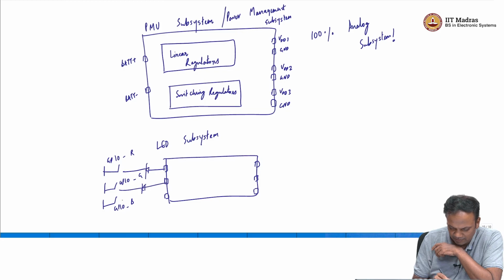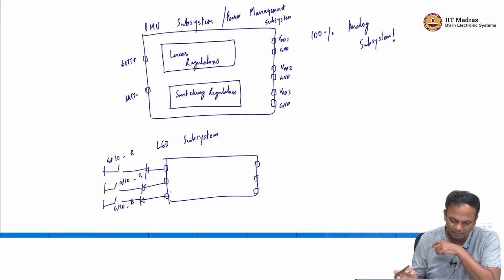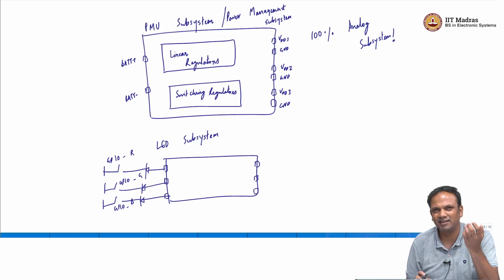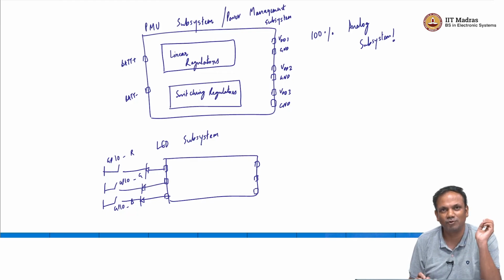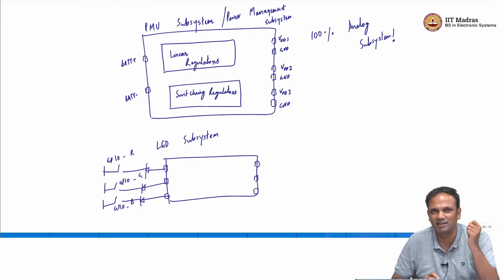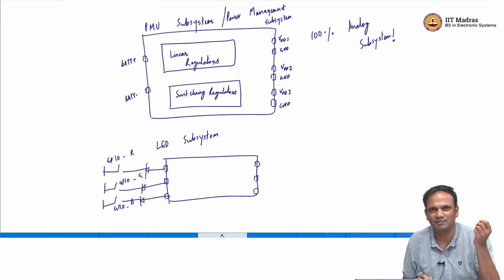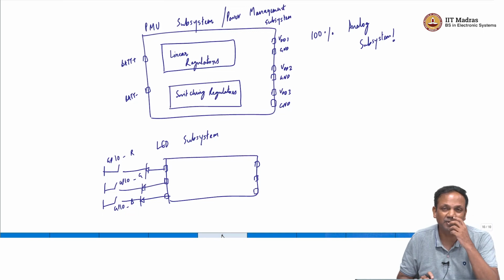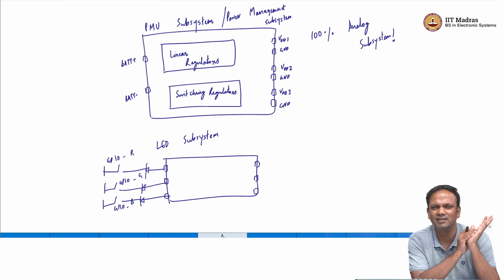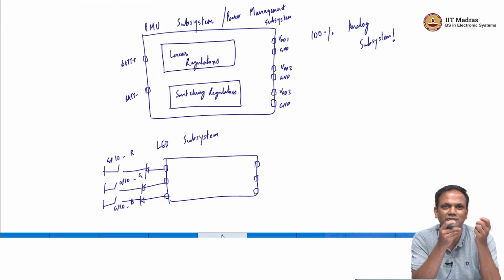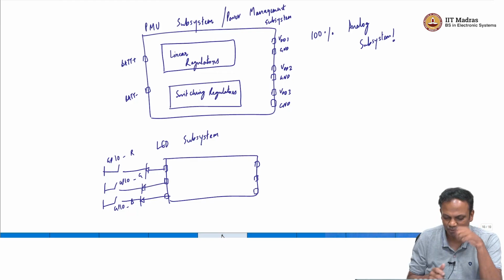So, you have the different LED lights here, and these lights need to be driven from the supply now. The way LEDs glow is that you flow current into a diode, it will glow. So, the simplest way to generate a current is to have a supply and a resistor. It is not a perfect current source, and I think that again you might have covered in this class earlier. But for the purposes of visual indicators, it might be the simplest system to build.